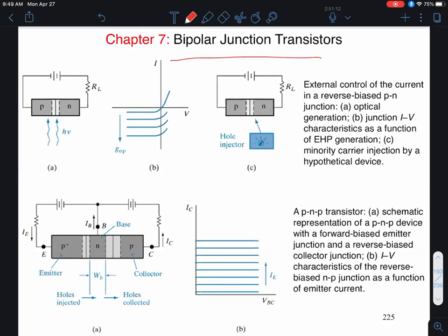inverter example that I showed you, when you have these Boolean gates, if I have NMOS and PMOS work in tandem, you'll always have either the NMOS on, PMOS off, or vice versa. And as a result, CMOS chips end up consuming very low electrical energy, okay? Low levels of electrical power. And that's what enables you to make these complex chips with billions of transistors without draining your battery in your cell phone or burning up your chips, et cetera, okay?